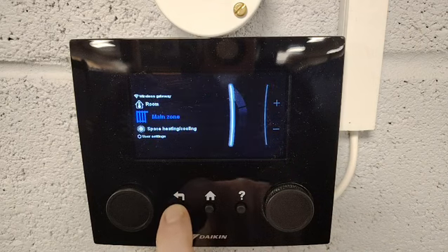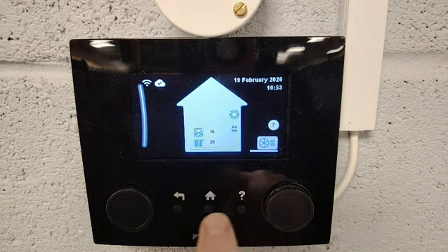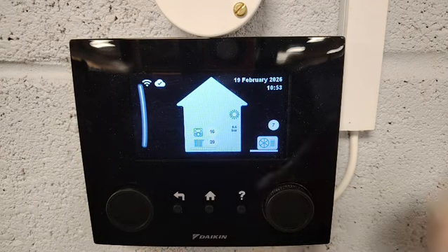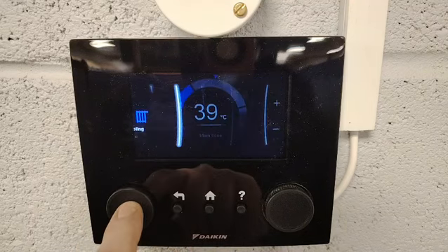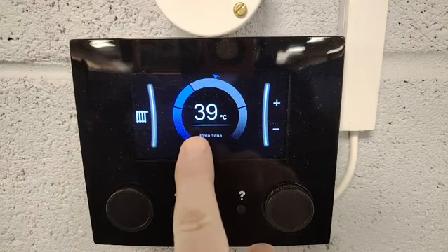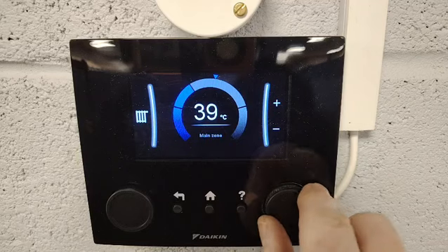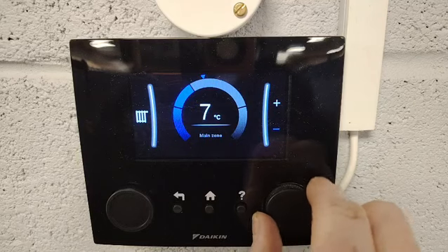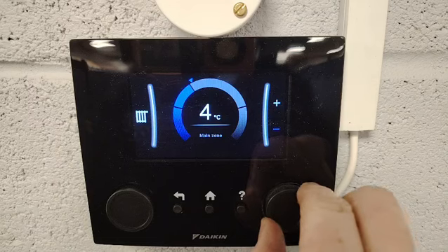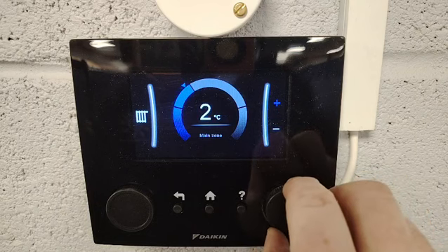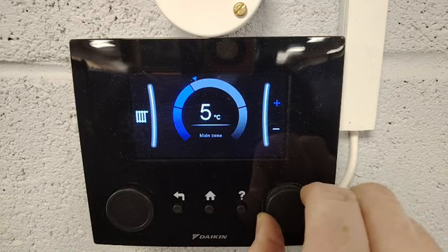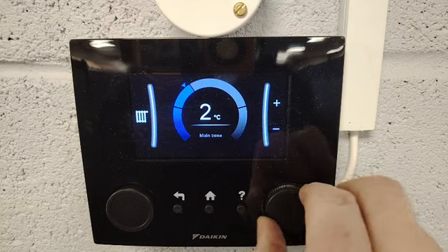Enter. Come back, and what will happen is the heat pump will then give 10 degrees more flow temperature. If we go back into this and you want to adjust it again, you'll see it was from 29, it's now 39 degrees, because we've added 10 just for simplicity. But we can bring that back and we can make that actually a minus if we wish. And a little arrow indicator that you can see moving gives indication as well of where the set point is.